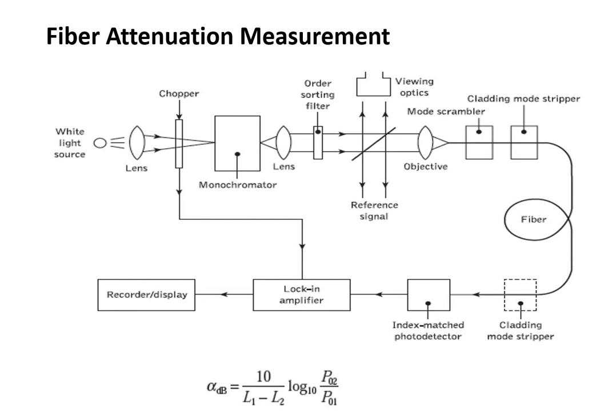Normally, the plastic jacket covering the fiber over a length of 50 mm is removed at the input end and output end of the fiber. Then the fiber with the jacket removed is placed in an index matching liquid whose refractive index is slightly higher than that of the cladding. This arrangement is called a cladding mode stripper, which will attenuate the light propagating through the cladding.